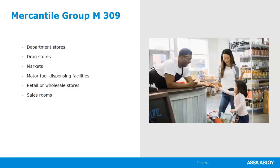Group M, Mercantile, is very similar to Group B, Business, but instead of selling services, you're selling goods and merchandise. So department stores, drugstores, sales rooms, very, very similar to a Group B business occupancy. And ordinary hazard, ordinary risk, and therefore Group M, Mercantile, can use delayed egress on the side doors. You think about stores, you don't want somebody stealing something and going out the side exit door. The exit door is there in case of a fire, but you don't want somebody just running out that side door with merchandise.